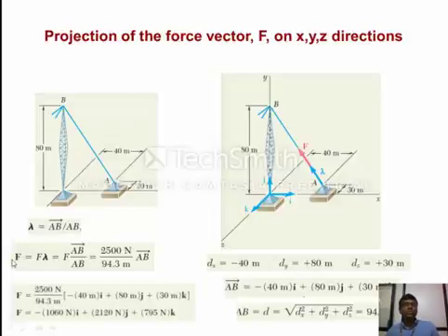Now you look at the force. We don't know what that is, it's the vectorial component. We know the magnitude, 2500 Newton, from the problem. So the magnitude of the force is 2500 Newton. Now what you have to do is F into the AB vector divided by AB, that is lambda. So you convert that and resolve it into F equal to minus of that component, this is Fx, this is Fy, that is Fz.